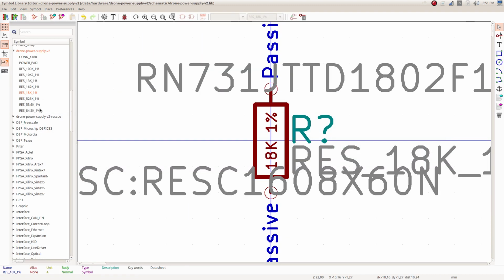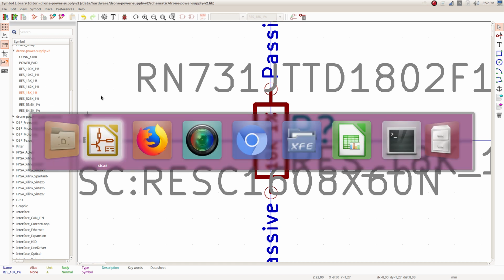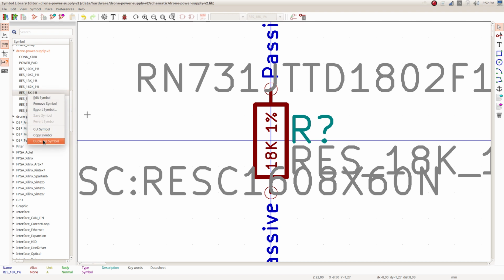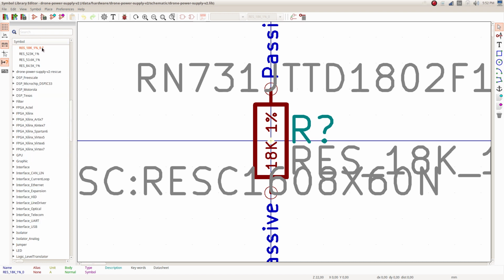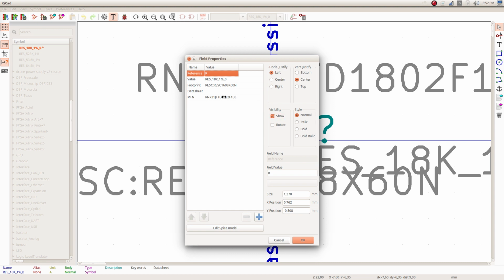I'm creating the library before actually swapping out the components for the new components that I'm creating in this library. Right now I'm going through the components and pasting in the manufacturer number, because I already have that in an Excel document, but I don't want to have it in an Excel document. I want to have it in KiCad. So I can go back here and duplicate this resistor, double click on it, and then set the manufacturer number.